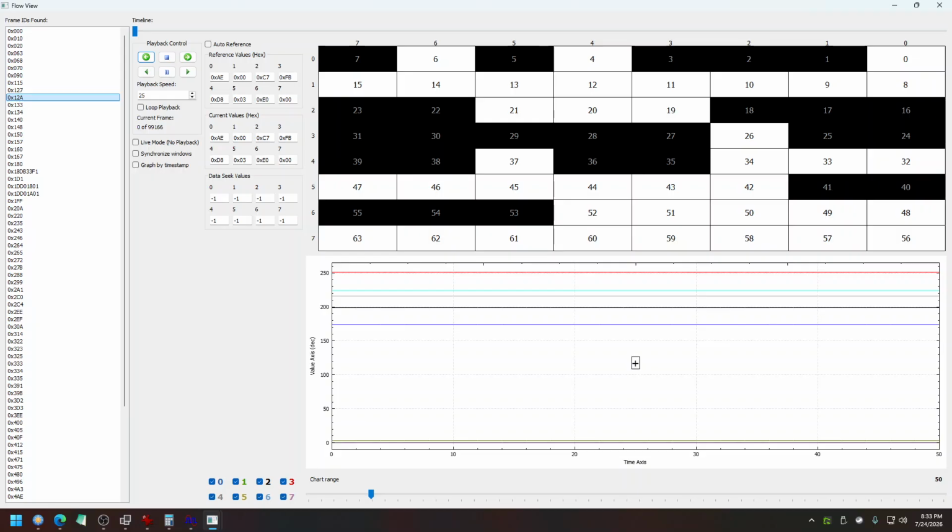This is not the right way to do it. You're really supposed to take the vehicle and interrogate it while it's sitting in the shop on a lift. Do one signal at a time. Like heat the coolant temperature sensor and watch what it does, or spin the wheels with the transmission in neutral and see if you can get some information from the ABS sensors or from the brake control module, the ABS module. Try to figure out the information that's being transmitted that way, right? But we don't all have the luxury of doing that. I don't even have the luxury of doing that.